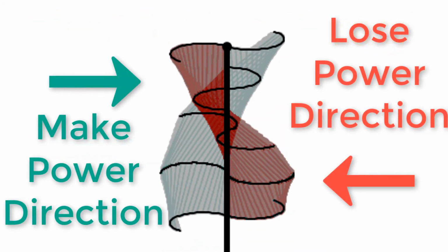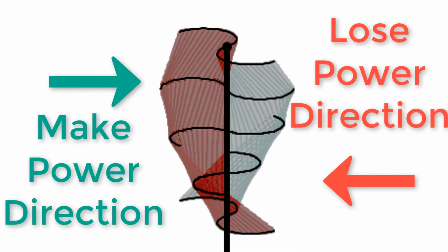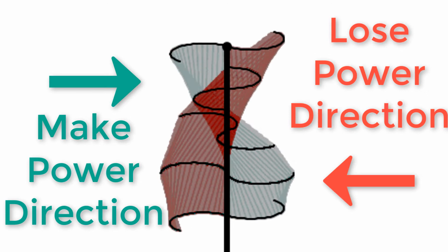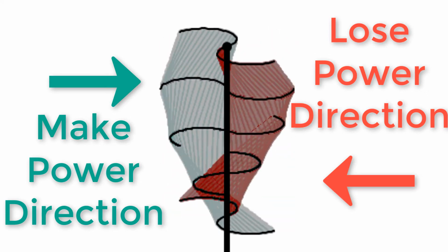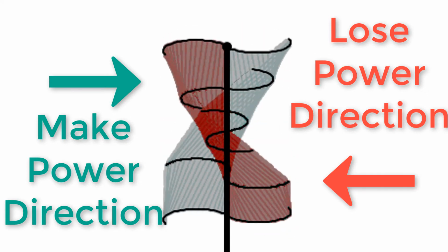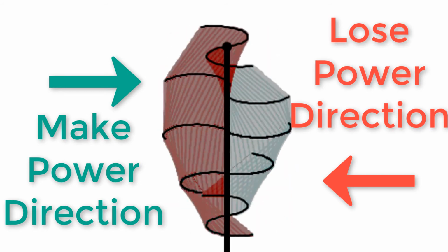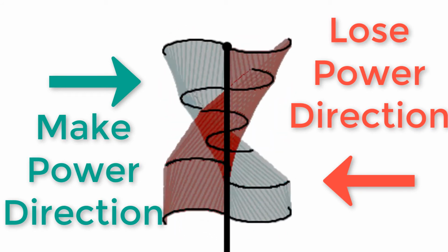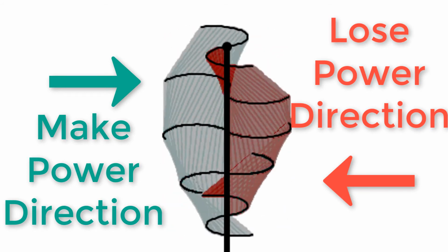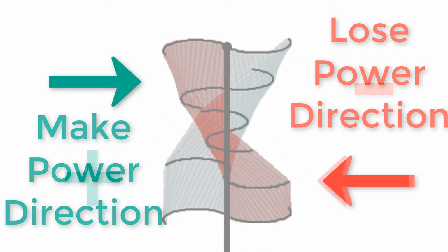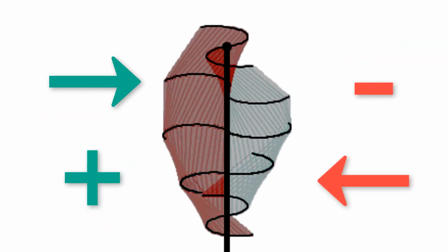For the other half of the cycle, it has to come back upwind, and this is where we lose the energy. So the wind is blowing into the cup, and we're harnessing that energy, and it's spinning the turbine around, as you can see on the picture here. However, once it gets past a certain point, it has to go back upwind before it can start to harness the energy from the wind again. And this is why the efficiency is so low for a vertical axis wind turbine.